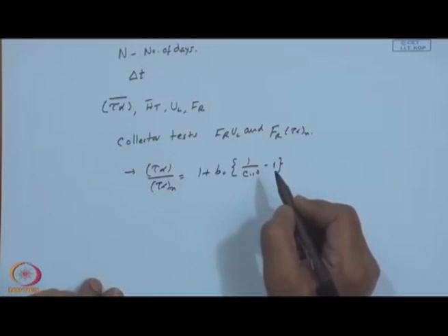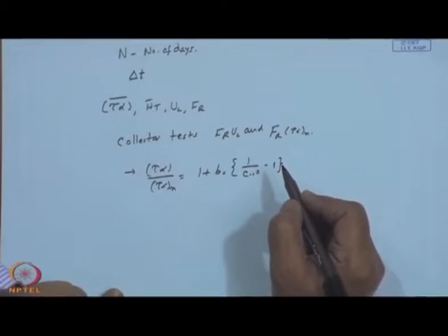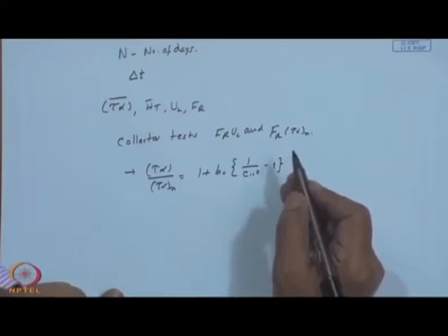And you have got the effective angles of incidence for the direct radiation in the form of a graphical representation, or the effective angle of incidence for the ground reflected radiation and the sky diffuse radiation, which are constants, they do not change with time, they are a function of the slope beta only, that is your theta g and theta d. So, one can estimate your tau alpha bar as per the relations which we have already dealt with in detail.